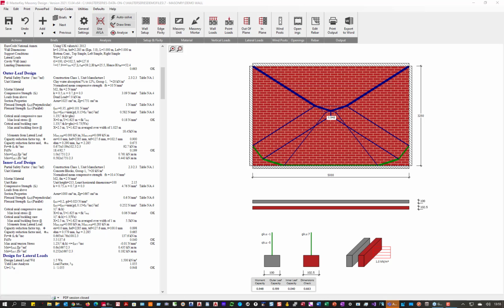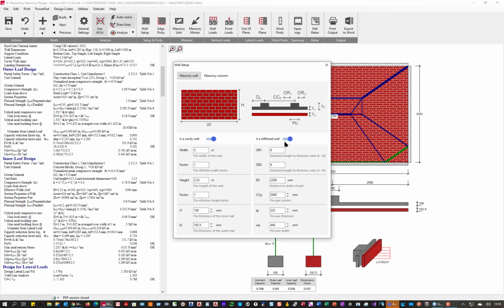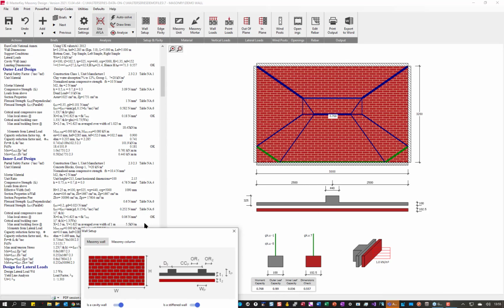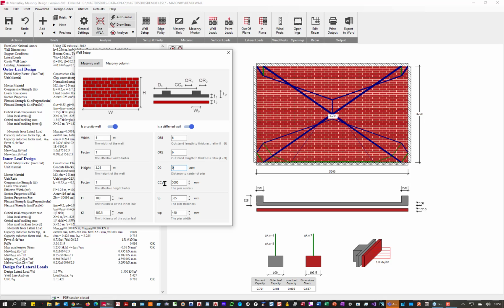Can the piers be set at different centres? Right, that is not at this moment in time possible. What you've got in your wall setup is basically, it's not a fiddle, but you do have the ability to say where the first pier starts, which is D0. If you put that in as nothing, it's going to try and assume them to be centered. So if I put that in 5 meters apart, it's going to put half up here and a half up here at either side.